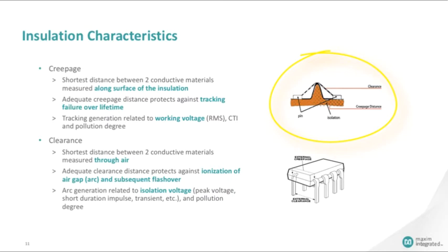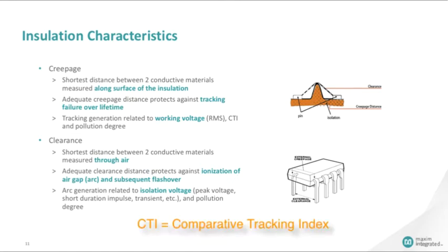the insulation. Tracking is the process that produces a partially conducting path of localized deterioration on the surface of an insulating material as a result of electric discharges on or close to an insulation surface. Tracking damage in the insulating material normally occurs because of one or more of the following reasons: humidity in the atmosphere, presence of contamination, corrosive chemicals, and even the altitude at which the equipment is to be operated. The degree of tracking depends on the Comparative Tracking Index, or CTI.